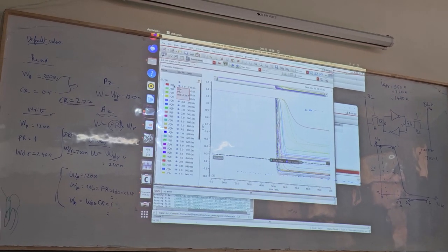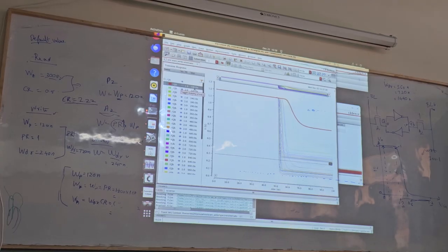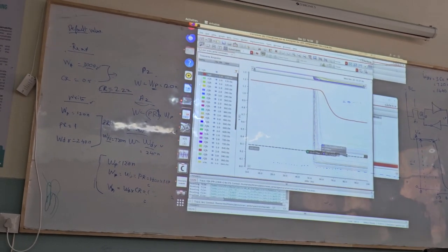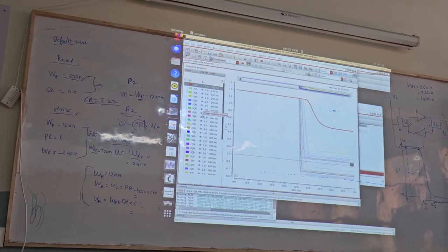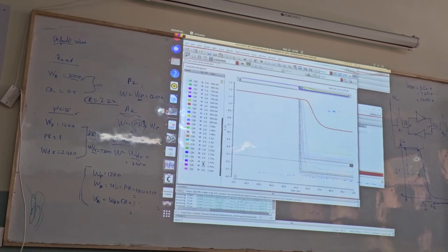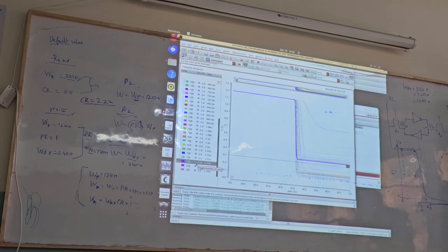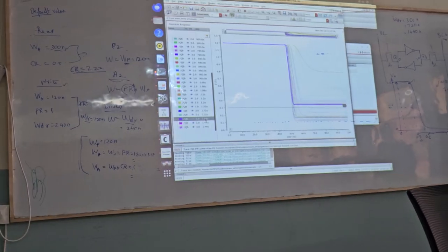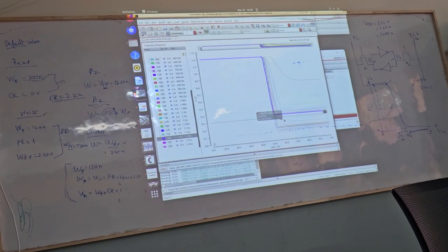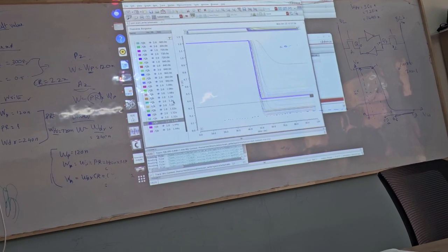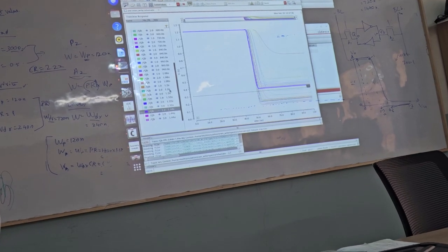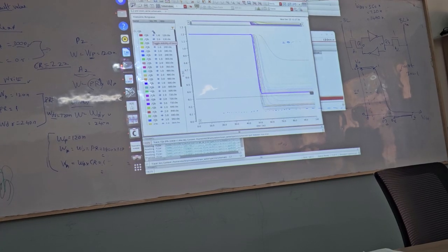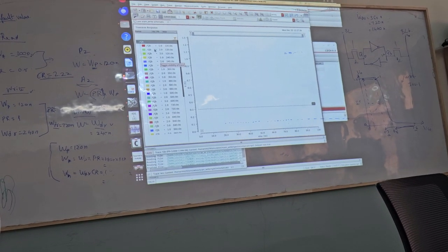Now, when I have this PR of 1 and WDR of 120, the graph is way away from the desired horizontal line, right? We will also select the one that has this one. So even in this case, a PR of 1 with the maximum value of 1440 couldn't cross this desired result. Which means the PR of 1 never helps us to bring this Q bar less than 300 millivolt. Is that clear?